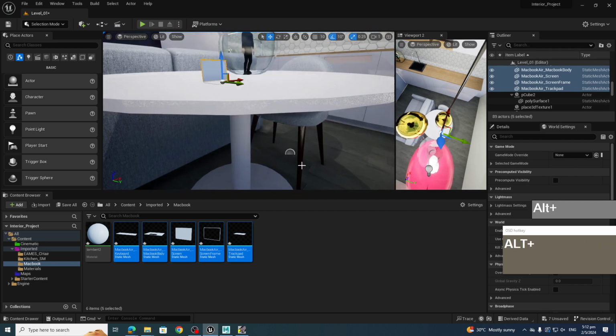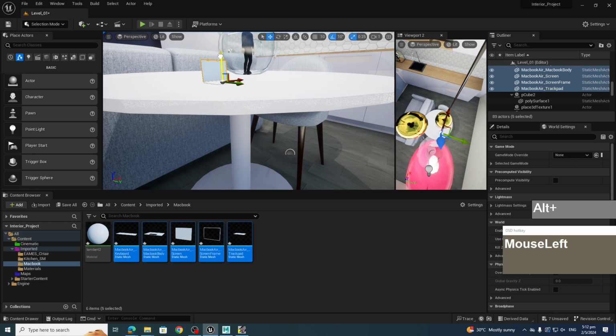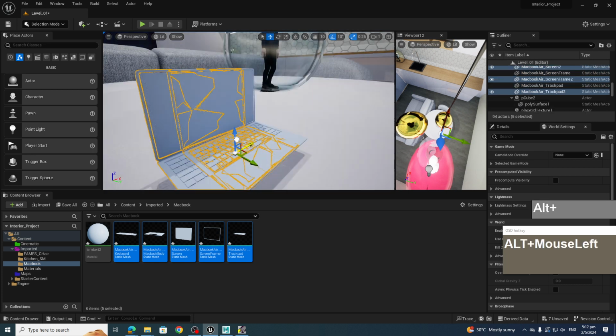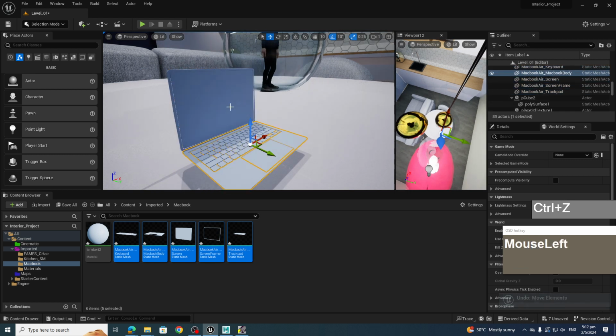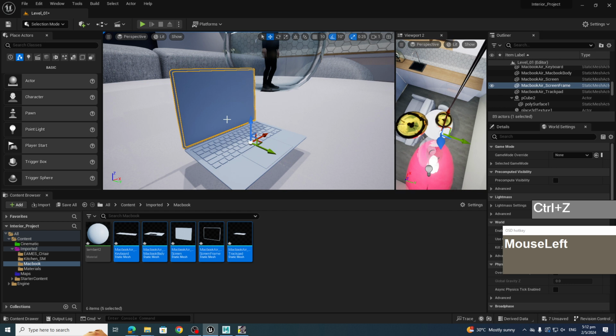My MacBook is very tiny. Okay, I want to show you this tip right now. If we press T to observe the center point of each of these objects, you realize now you can see the transparent glass objects. So I select it and press F to go to the center. If you ever have a situation where you cannot select every transparent object, you just need to press T. The pivot point has been messed up already.